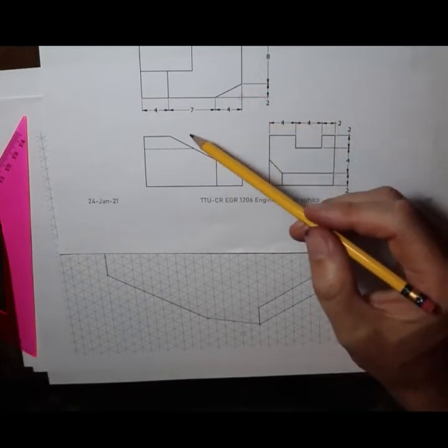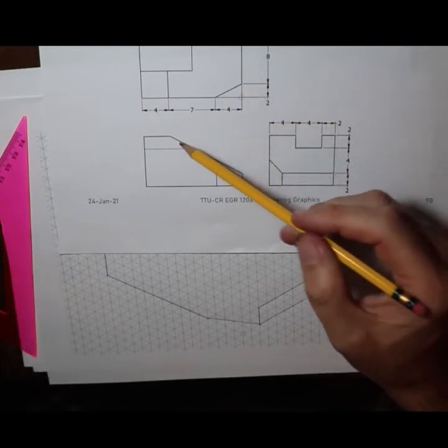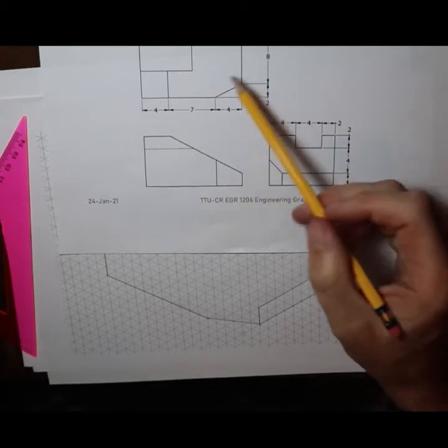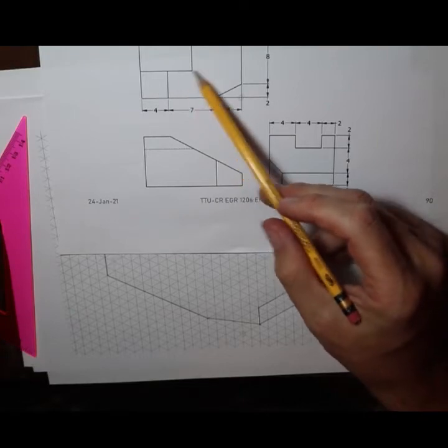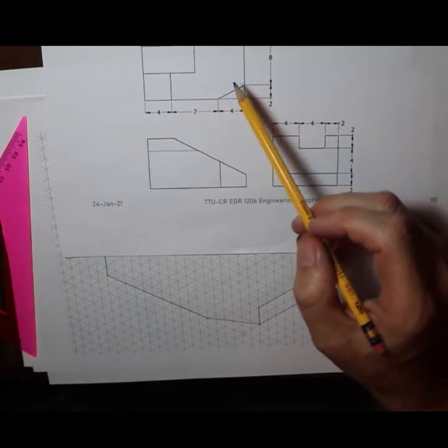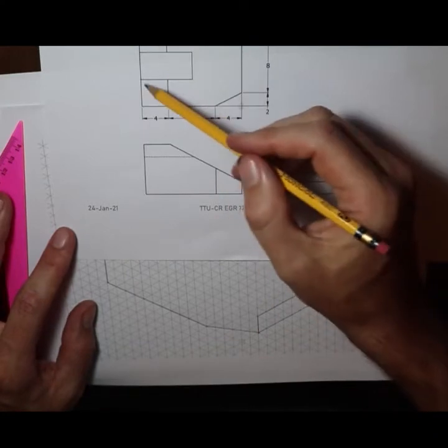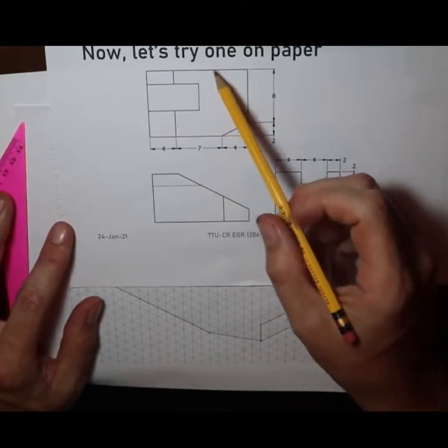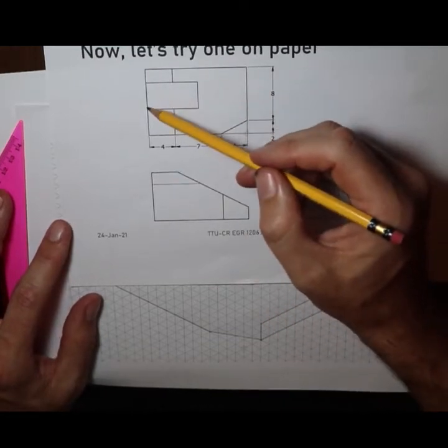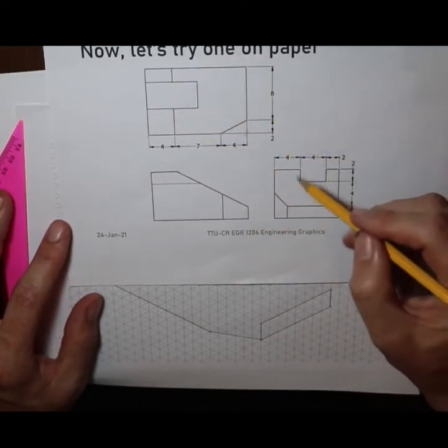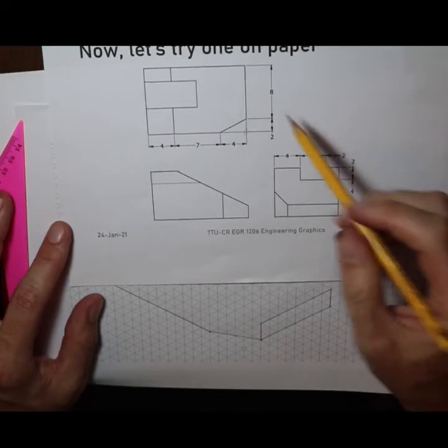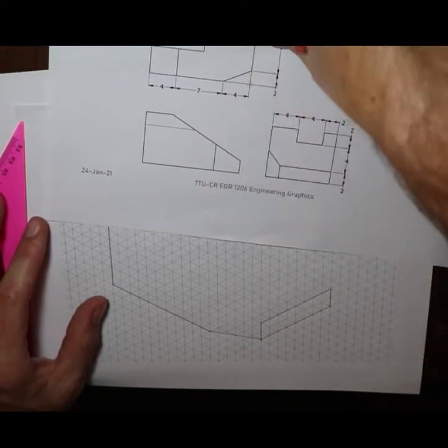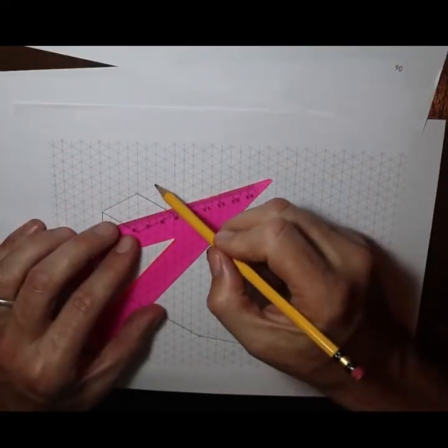Now the kind of tempting thing would be to say like, well, we have this point and we have this point and they're straight and we can just draw down. But if we look here, then we see that is not the case, right? We have this kink in here, so we have to wait for that. But we can continue up here. We can basically get ourselves all the way over here to start drawing this edge. So what we'll do is we'll kind of do a jump across here because we know there's a hole. So we'll jump 4 and then we'll draw this edge, which is 2 by 4. So it's a jump 4, 2, 4.